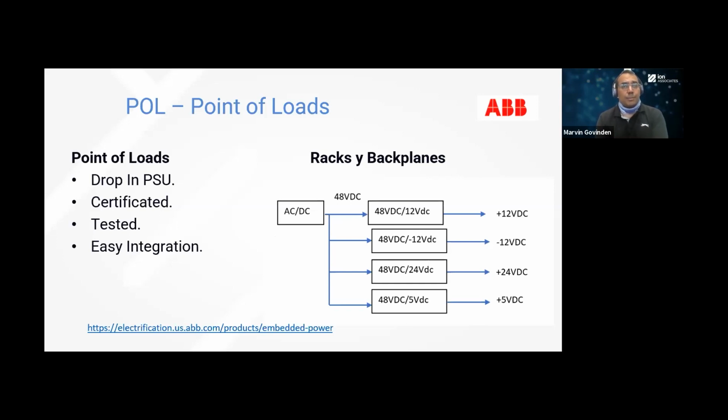If you just drop in bricks onto your designs and everyone who's working on a card uses the same bricks and the same power supplies, you've normalized the design. The volumes are better. You're buying more of one part from a supplier, so you can negotiate better costs, and the performance, be it good, will be replicated across the board, which means your calculations for FIT rate and mean time before failure can all be normalized and standardized. So there's a big benefit to dropping in a brick onto a design.